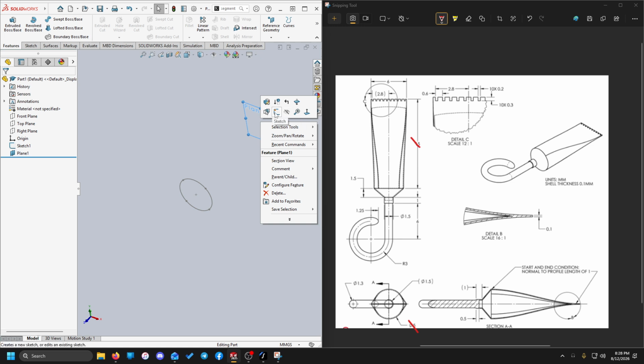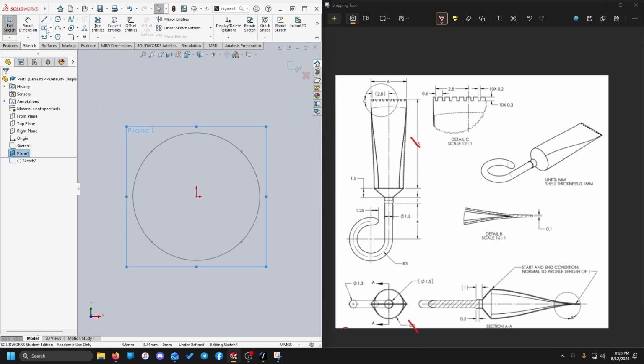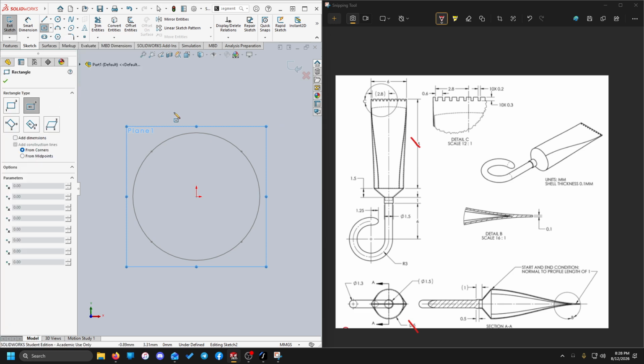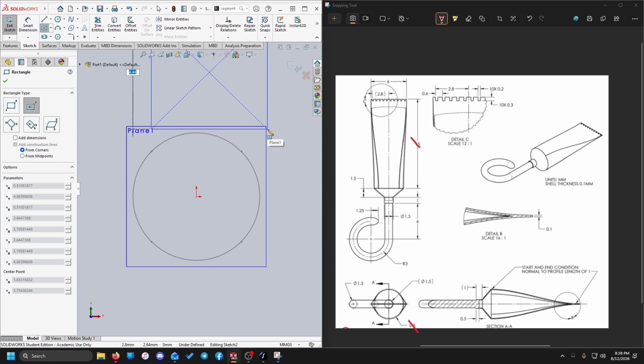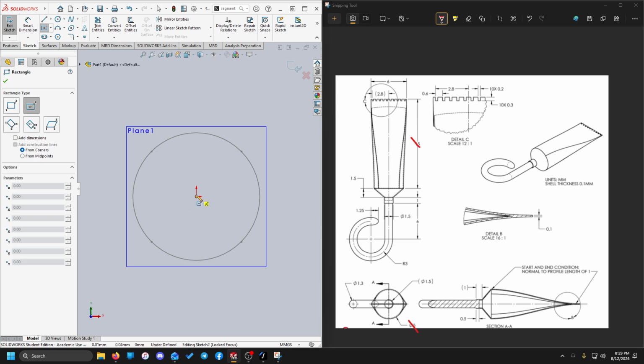Now we've got our rectangle. So we're going to create a new sketch on this one. And for that, we can do a center rectangle. So this one's in the drop-down next to the rectangle tool, center rectangle. From the information that we're given, we don't really have anything implying that it wouldn't sort of keep this level of symmetry to it. So we can pretty much assume that the rectangle is going to be centered at the same point as the circle.